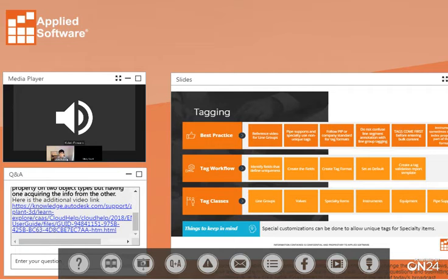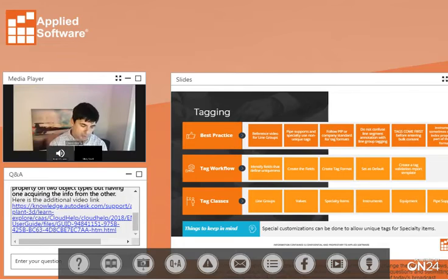So that's very important. Then instruments sometimes need an index property as part of the format tag. Dave, you want to speak to that a little bit? Yeah, in certain cases, with interlocks and other types of instrumentation, frequently you have the same field value shown, like FI 1001 might be used in a couple spots, but you actually have multiple instruments.